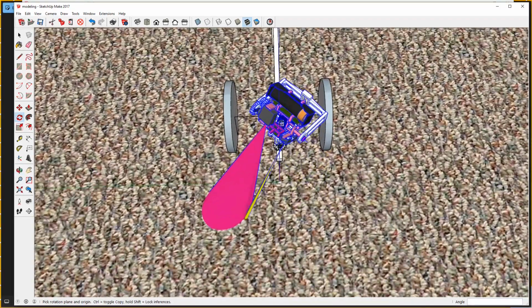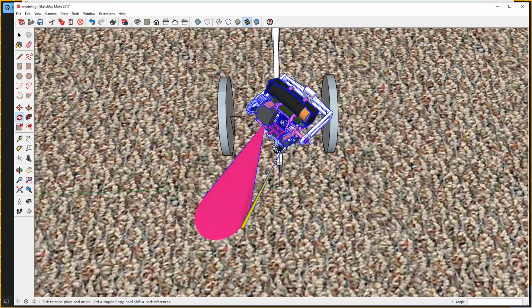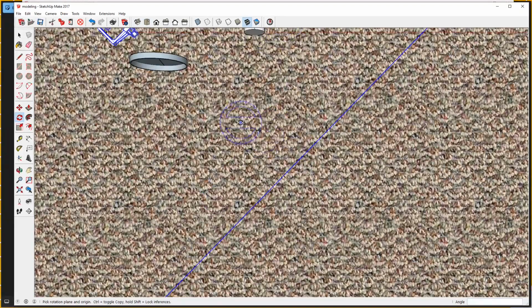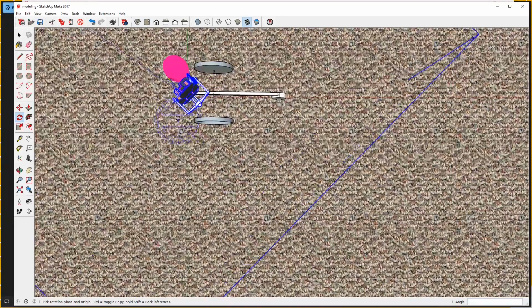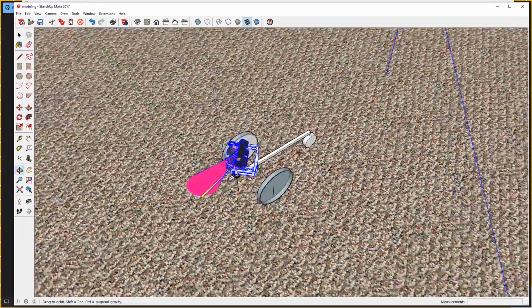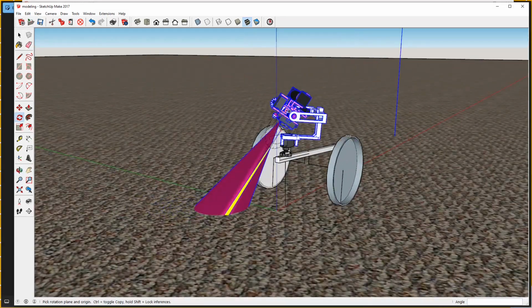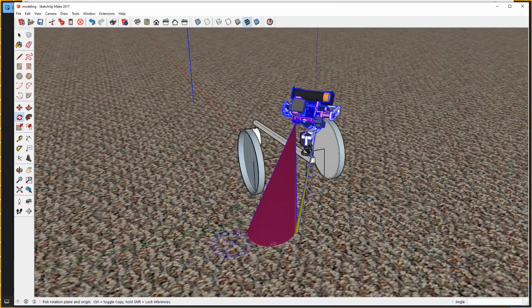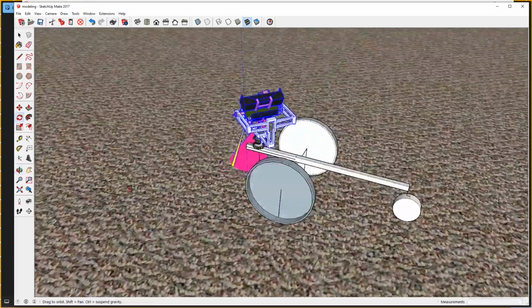And also, while the IMU is supposed to capture the rotation, it's not that accurate, so I will just calibrate it with a compass in the real world. There'll just be a compass on the ground, and I'll turn it to the specific degrees based on the width of these beams. But anyway, when we scan this floor like this, and we get the expected values based on geometry, like here to here, say it's 9 inches, then we go farther out 11 inches. If all those values are the same, then the world is clear, right?